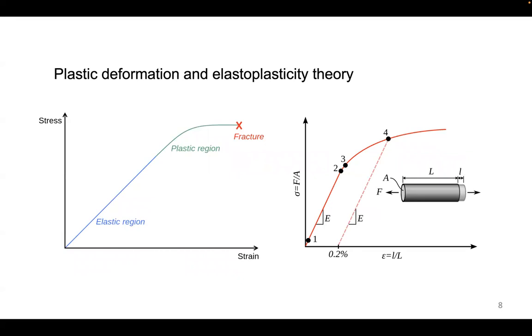And one thing that we mentioned last time is that if a material has plastic behavior, it has memory in the sense that if I load the material from the initial state to a point and then unload it, I'm not going to go back to the original path. So what it means is that even in the 1D case, I cannot write simply a function that maps strain to stress or stress to strain. Okay, even though the slope never becomes 0, because the path itself has an effect on the resulting behavior.